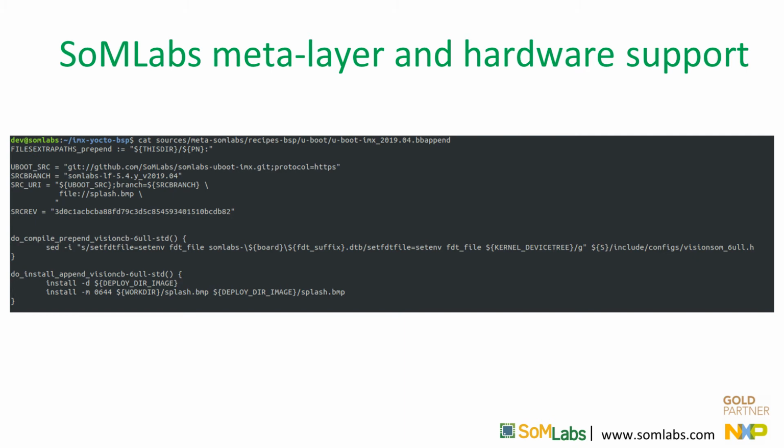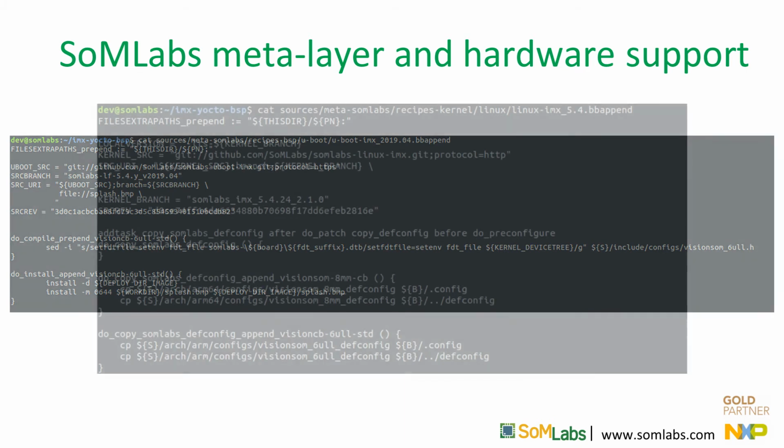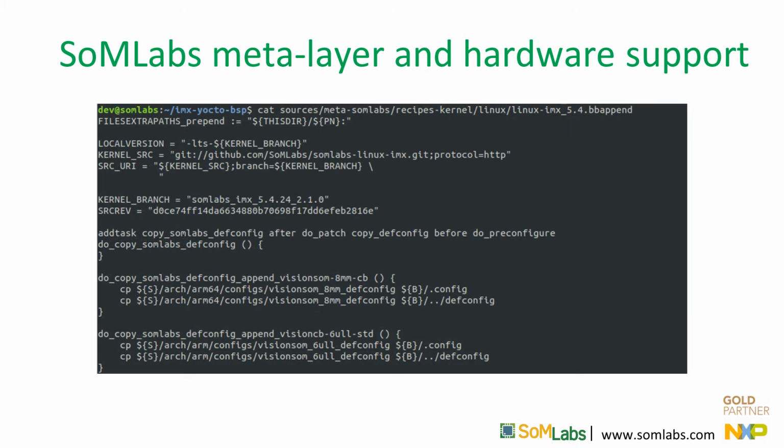Moreover, we can see that the build procedures can be performed conditionally depending on the defined and selected hardware. In the kernel recipe, the configuration file is selected this way. The do_copy_SOMLabs_devconfig procedure, performed after the do_patch and do_copy_devconfig procedures and before the do_preconfigure procedure, is responsible for this.